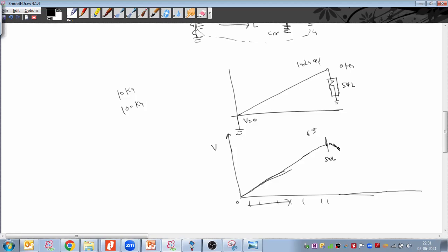In the next section again, we are taking the cable and getting a similar kind of voltage. Again we check the voltage, 65 volts coming, break the sheath, then take another portion of the sheath. Then we keep continuing, and when we reach the last section, at that moment we can do a solid grounding.